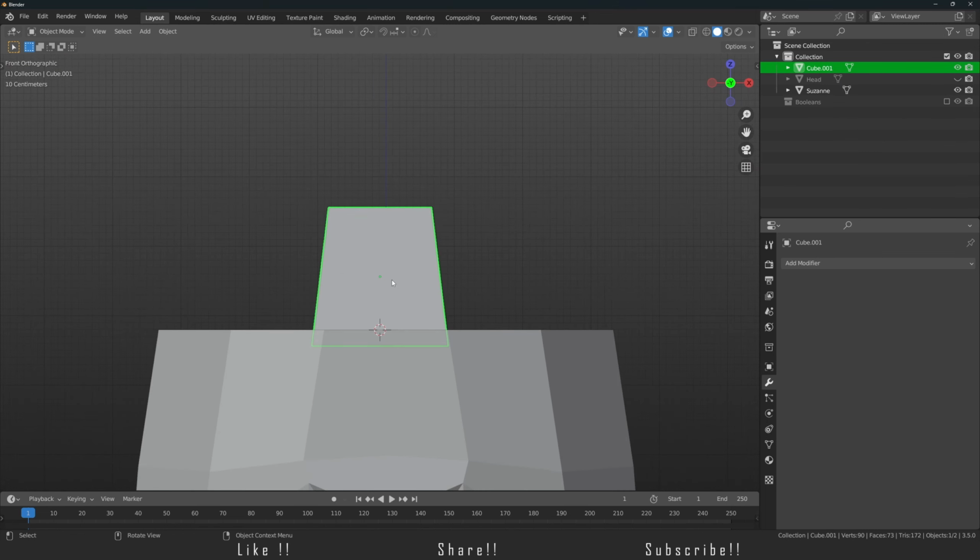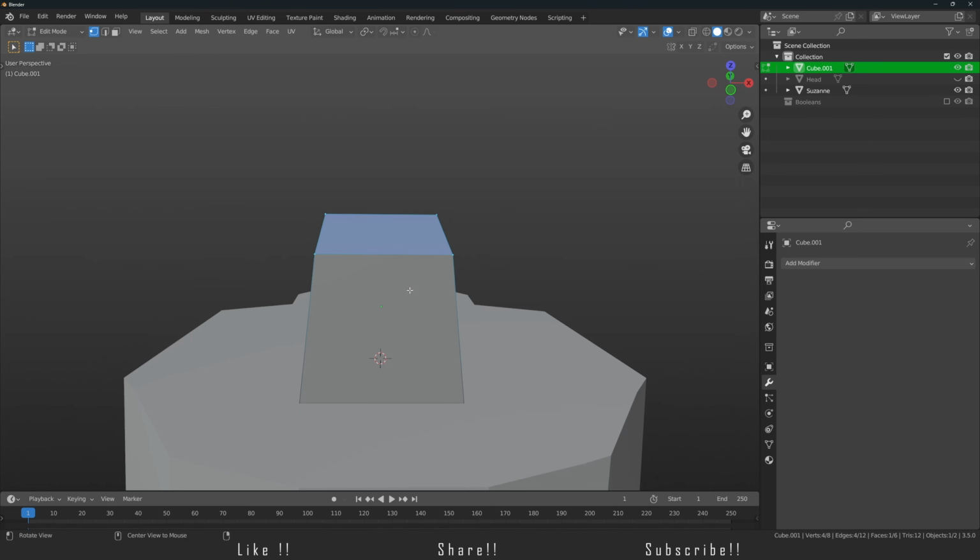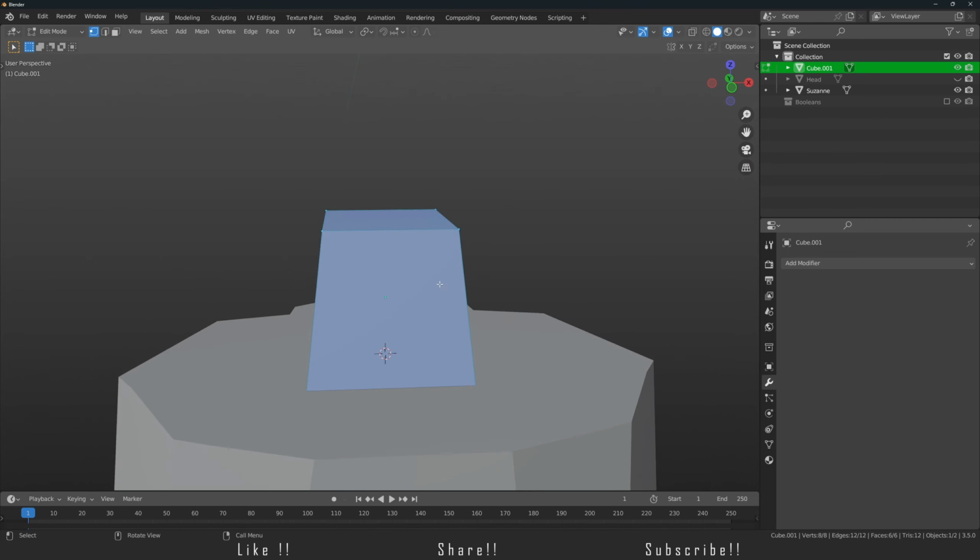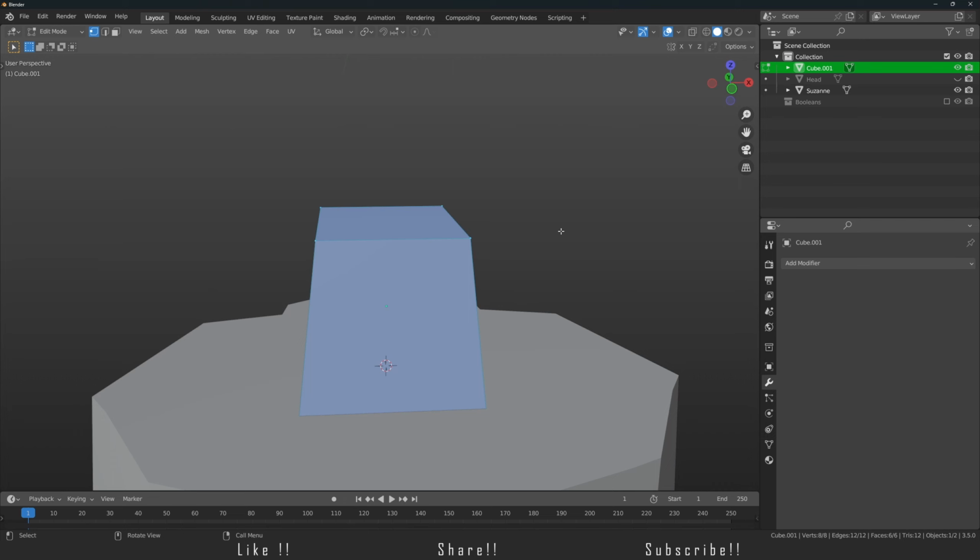Now, one of the things you need to realize is you need to make sure that you shrink down the male key now, because if this is going to be at the same scale as the female one, it could potentially be harder for you to put this into the female key. So what you want to do, you basically want to shrink it down a little bit. So press Alt S and then shrink down a little bit. Maybe I think this much is going to work.